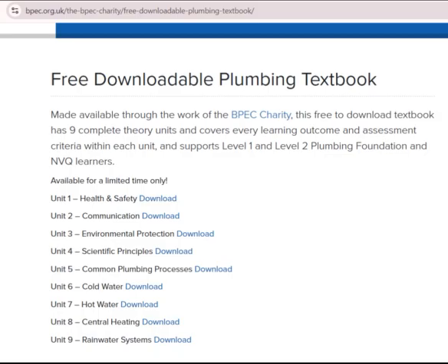Glycol is available in 2 forms: ethylene glycol and propylene glycol. Propylene glycol is the preferred solution as ethylene glycol is highly toxic. Fuel oils. There are many different fuel oils. However, most domestic oil boilers and appliances use kerosene, known as C2 grade 28-second viscosity heating oil. Kerosene is a thin, clear flammable fuel formed from hydrocarbons.